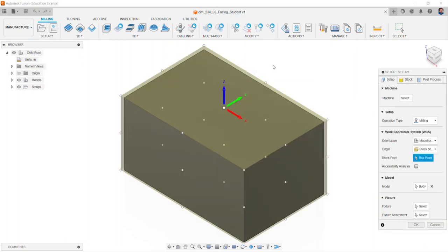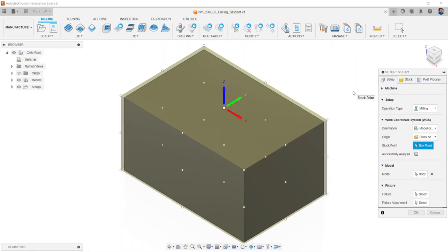Here, just to note, there are several settings that we're going to leave at their default, because some of them don't really apply to our milling operations, and also we're using material that's going to be pretty easy to mill and does not need a lot of industrial settings or tooling or toolpaths to be generated to make that happen. I'm going to go ahead and select the arrow next to On Machine. We can simulate with a machine if we prefer, but I'm going to select the arrow to collapse the menu to make this a little bit easier to handle. Okay, not as many settings to look at when we do so.